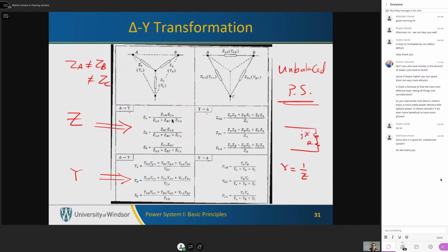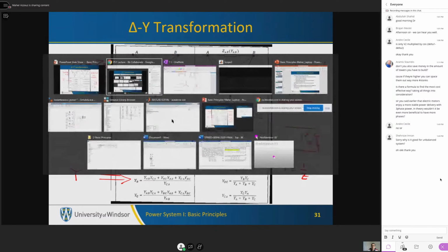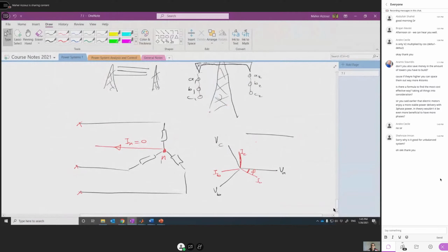And that is why I'm telling you, increasing the number of phases will increase the complexity of system analysis. So if we switch from 3 to 4 or 6 or wherever, this will add a lot of complexities. And even nowadays, when they invented the DC transformer, I mean, a power electronic device that is capable of stepping up and stepping down DC voltages, the analysis is way, way easier than AC systems. If we have DC systems, you don't need to worry about the reactive power.